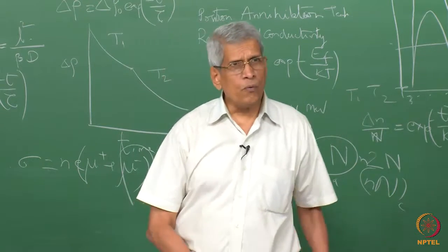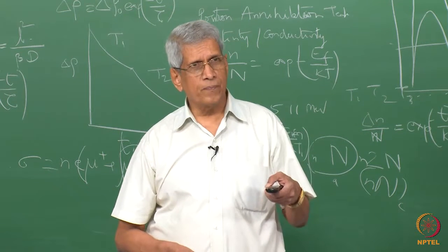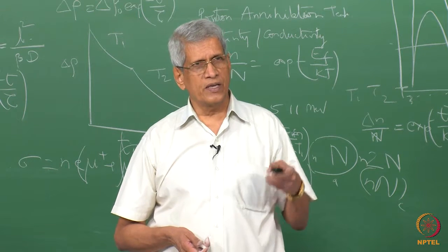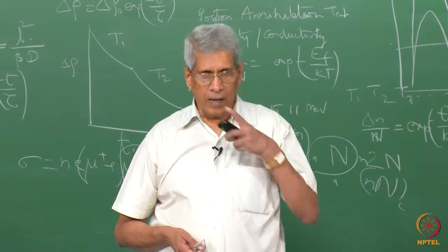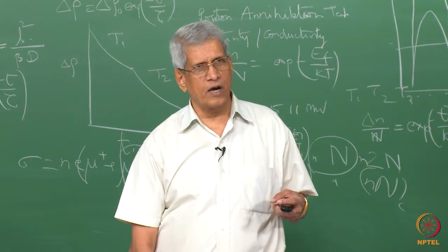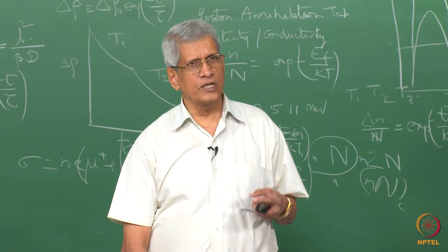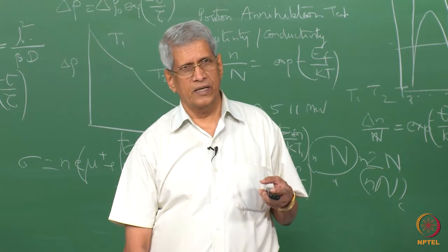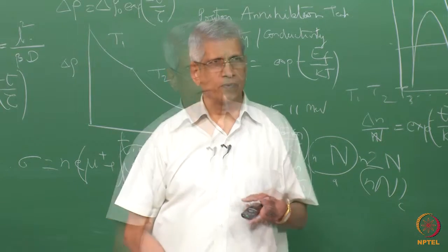Okay. Now, what we will do is that we will break here, then talk about how impurity concentrates. So, what we have considered so far is vacancy concentration in metallic material as well as in ionic materials, and how to determine it, we have discussed using various techniques. One is thermal expansion and X-ray diffraction, another is the resistivity technique, and another is the positron annihilation technique. We will stop here now.